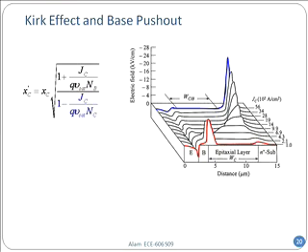And you can see that will happen when the numerator goes to 0. And when will the numerator go to 0? Well, numerator will go to 0 when the current is so much that it overwhelms the collector doping. Because whatever you had the collector doping, Nd plus, the electrons coming in, it is completely overwhelming the total number of carriers, and as a result, you don't have any junction. And this J sub k is in honor of Kirk, who in 1965-66 first explained this effect. Because of this, people couldn't push the transistor gain to much higher frequency. That I will come later. But this is your problem.